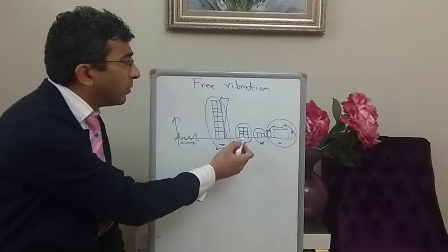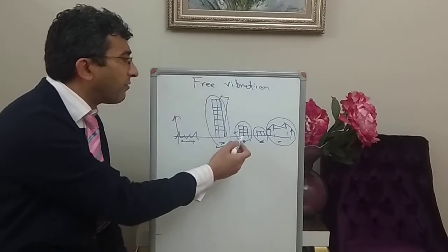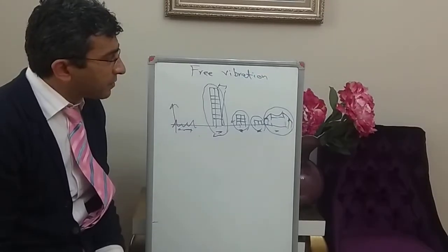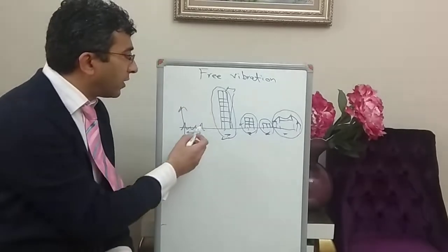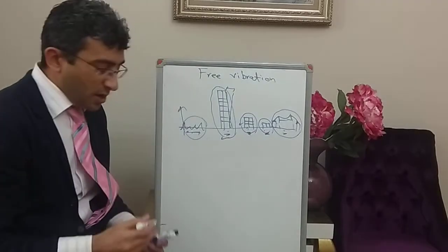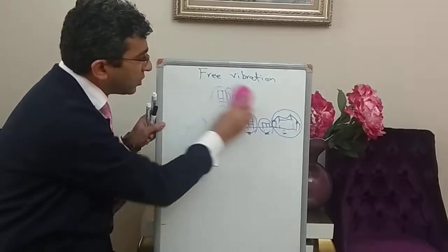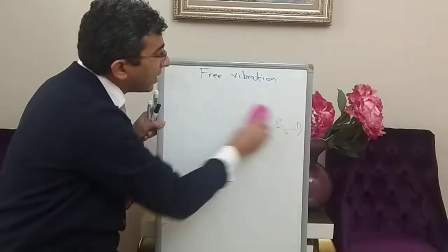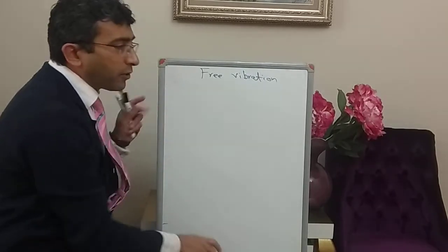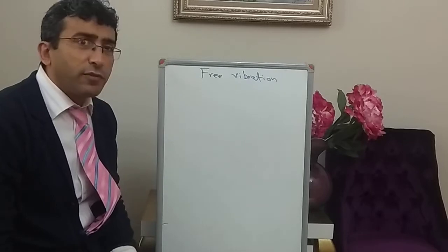So some buildings will be more affected. For example, mid-rise buildings will sometimes be more affected than high-rise buildings during earthquakes. So it depends on the frequency content of the shaking and the free vibration characteristics of the existing buildings. That's why engineers need to find these free vibration characteristics and need to study or measure them, maybe using what we call microtremor measurements.